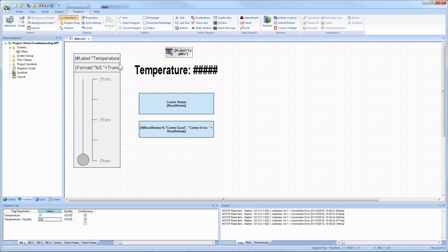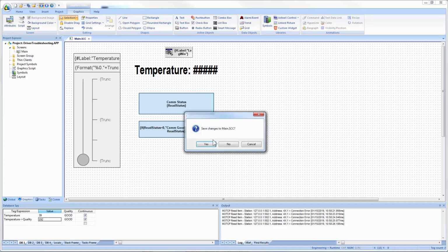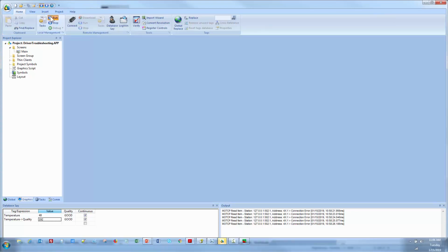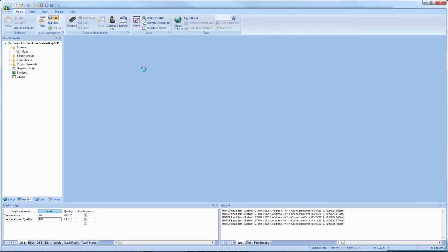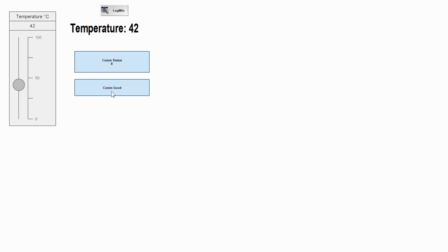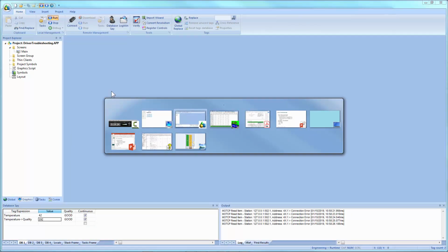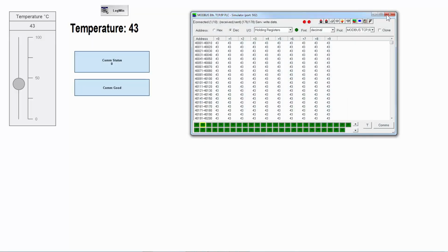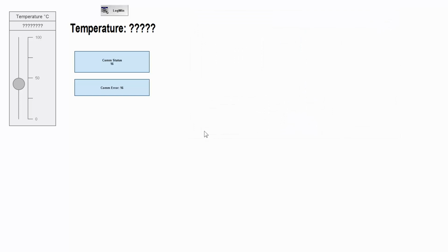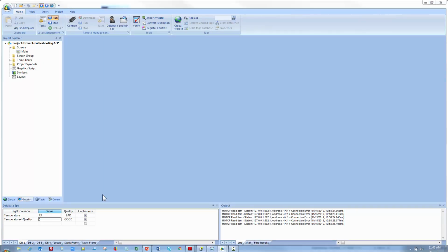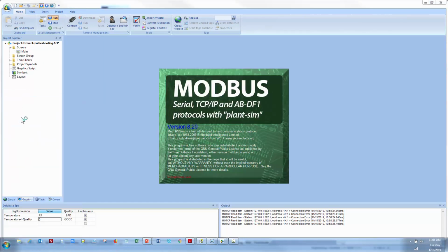And you could go on to say, look this up in the manual, or even display the messages that you'd find in the manual if you wanted. You could take this to all kinds of levels. So there we go, communications good. And if I disable the PLC again, we should see this com error 16, and that could say, call maintenance, things of that nature. So lots of different ways to handle that.